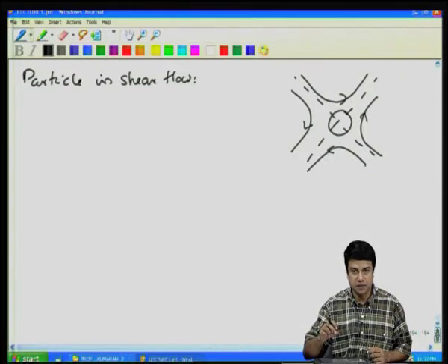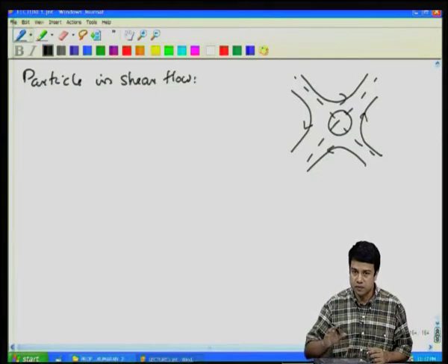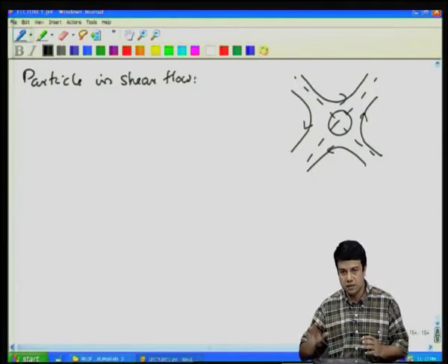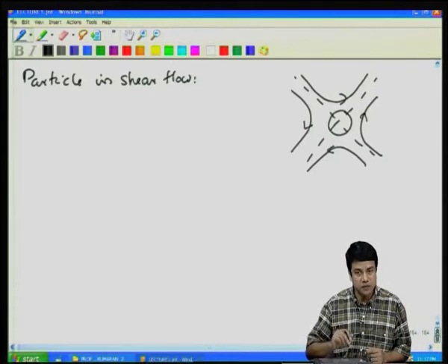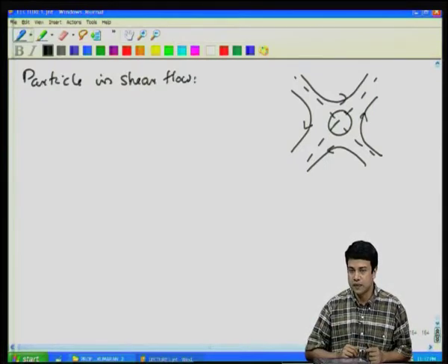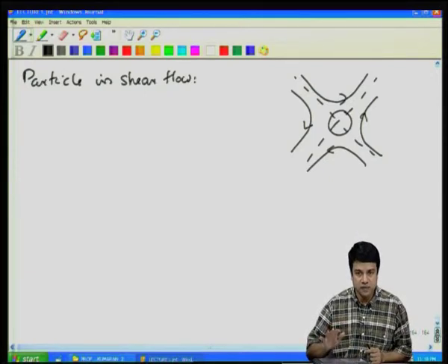That is always possible, because even if the particle is moving and rotating, I can decompose the flow locally into a steady translation with the velocity at the center of the particle, plus a deformation about that center. That deformation about that center can have two components: the symmetric traceless part of the rate of deformation tensor locally, which gives me the extensional flow, and the antisymmetric part which gives me the rotational flow. And due to linearity, I can add up the contributions due to each one of these, solve them separately, and add up the velocity contributions due to each of these.